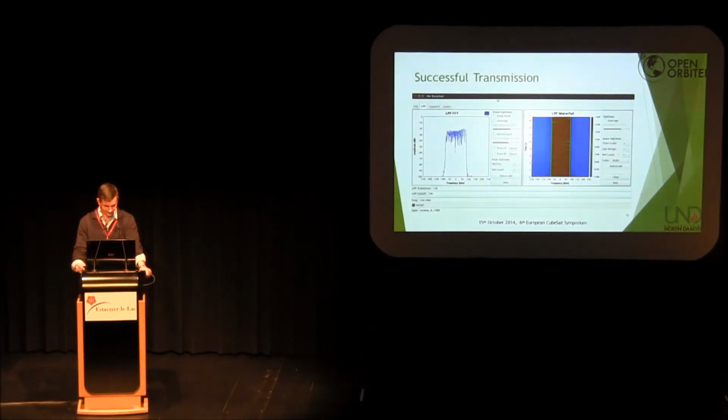Where we are today: we have tested FM transmissions from 24 megahertz to around 250 megahertz. The signal begins to break up around 200 megahertz and is unusable at 250 megahertz. We've also tested several different baud rates on the US amateur radio bands of 52 megahertz and 144 megahertz. We've been successful in transmitting at 300 baud to 2400 baud, with noticeable errors at 3600 baud and unusable at 4800 baud.